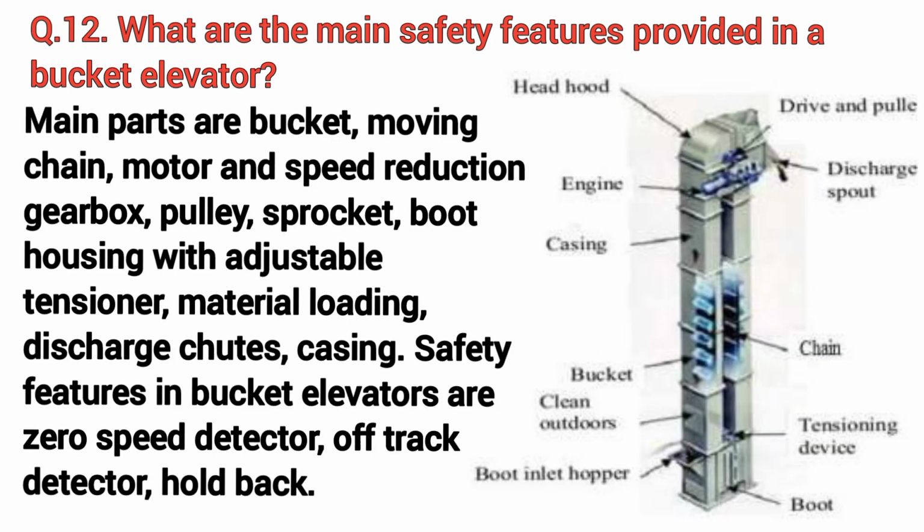Main parts are bucket, moving chain, motor and speed reduction gearbox, pulley, sprocket, boot housing with adjustable tensioner, material loading, discharge chutes, casing. Safety features in bucket elevators are zero speed detector, off track detector, hold back.